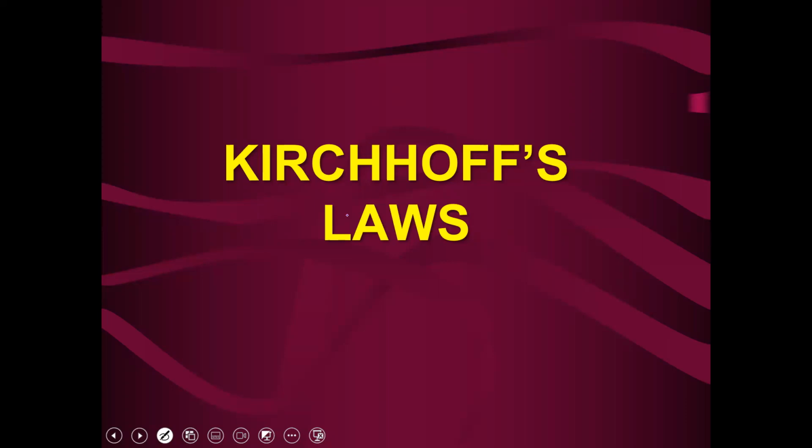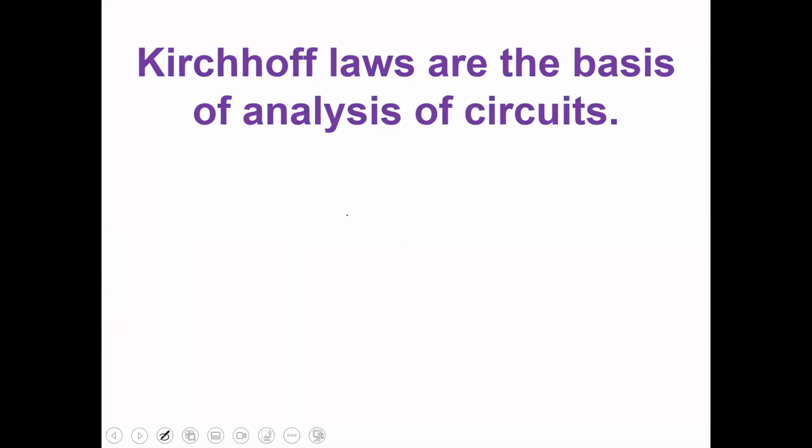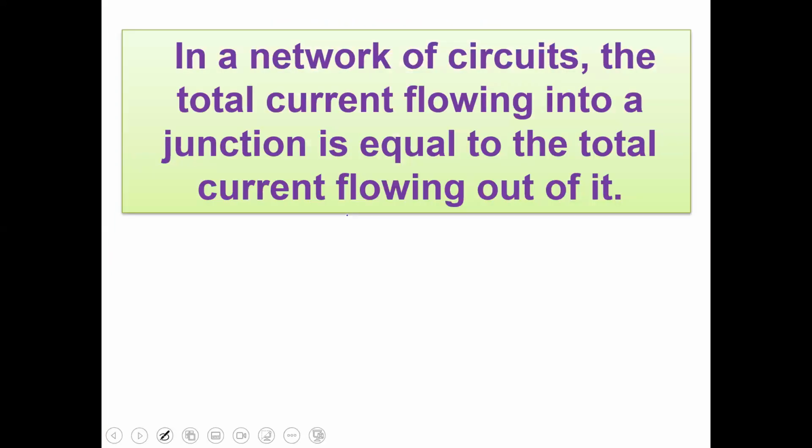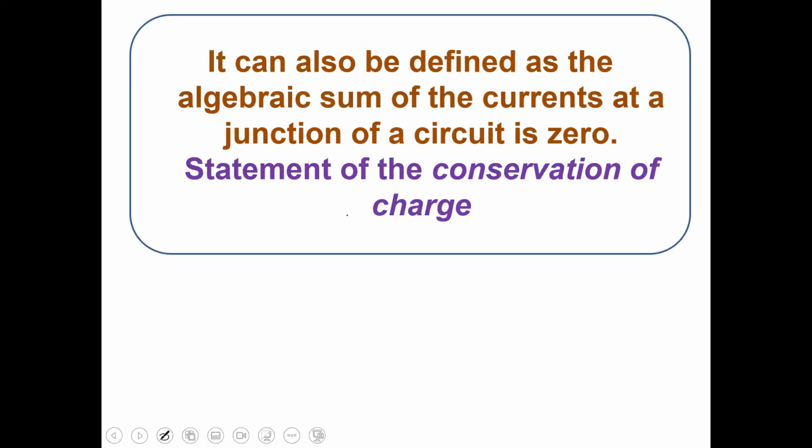Kirchhoff laws, give the heading. Kirchhoff laws are the basis of analysis of the circuit. The first law says in a network of circuits, the total current flowing into a junction is equal to the total current flowing out of it. This is conservation of charge.